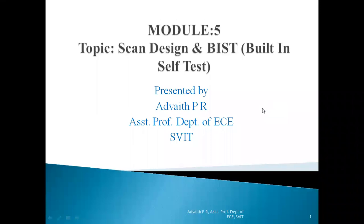In today's lecture video, I'll be discussing design for testability, and especially we will be covering a topic called scan design and built-in self-test. Normally, design for testability is categorized into three approaches: ad hoc testing, scan-based approaches, and built-in self-test. In this particular lecture video, our main focus will be on scan design and built-in self-test.